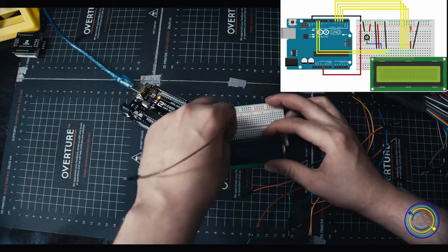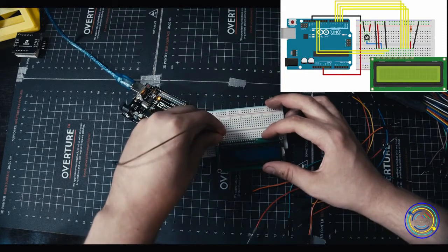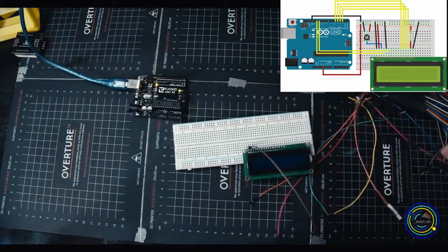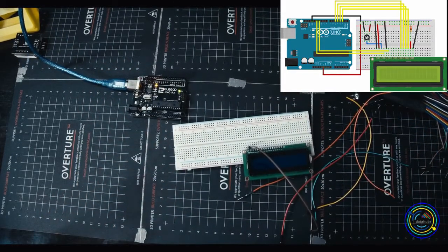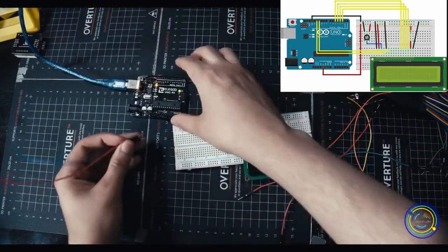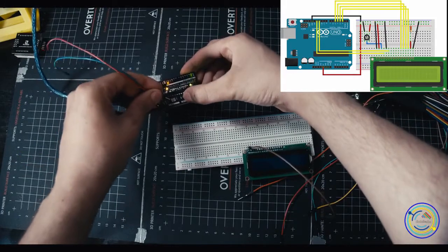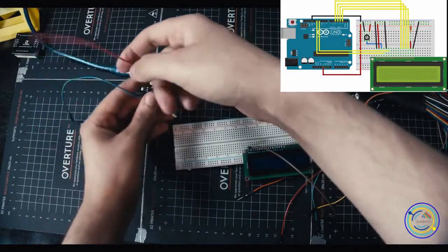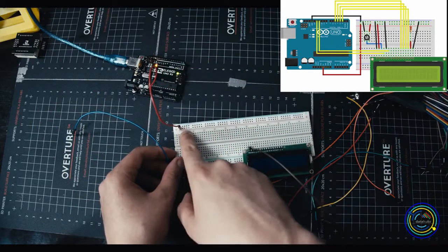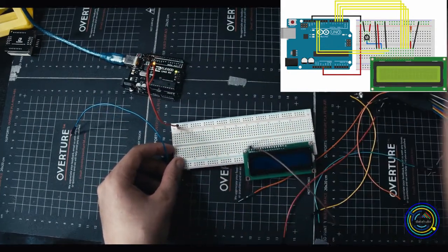This is our ground pin for the Arduino. Now one thing we're going to do that we don't usually do in our videos is take one cable and dedicate it to ground, and one cable and dedicate it to power. So we're going to go onto our Arduino, plug into the 5-volt with this red cable, and then plug into the breadboard on the red line.